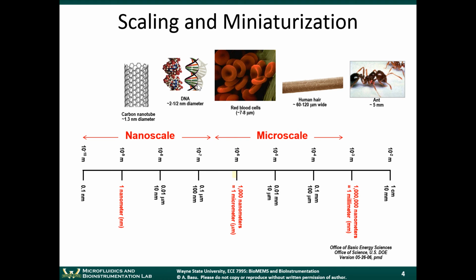Carbon nanotubes are strings of carbon molecules that have been arranged in a sheet that rolls around like this. You can actually make carbon nanotubes using a process called chemical vapor deposition. Carbon nanotubes have very interesting properties because the electrical conduction, the mobility, the rate at which electrons move through these devices, is quite high. Carbon nanotubes are conductive. So if you arrange a forest of nanotubes, parallel to each other, they form kind of a composite material. It's a conductive material with a very high surface area to volume ratio.